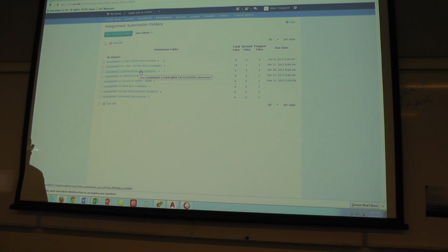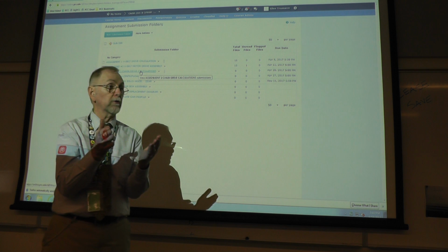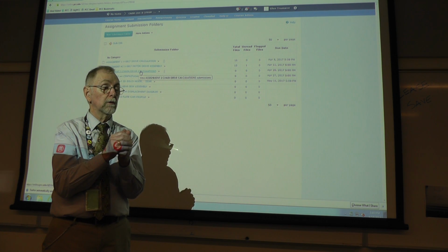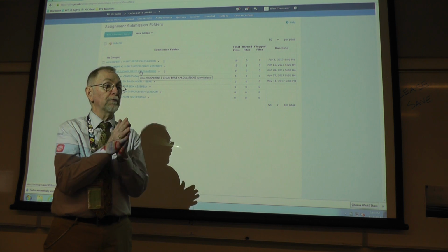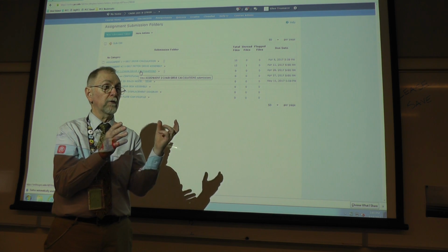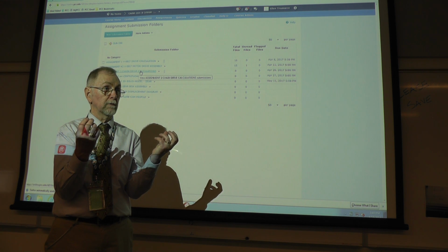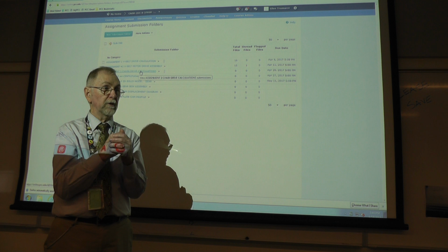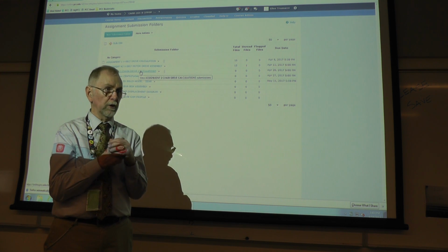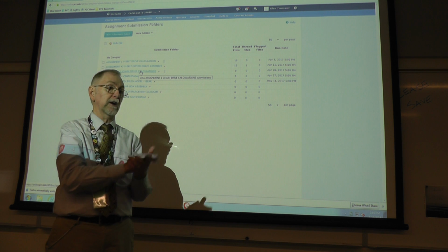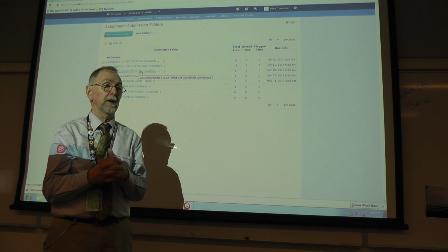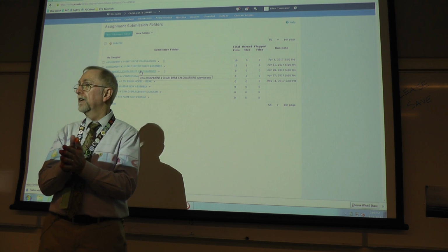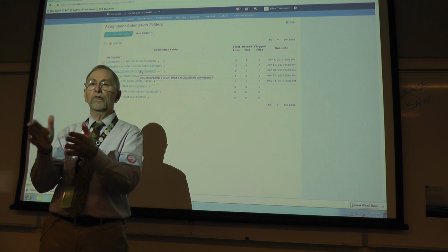Yeah. What does F look like? F is simply the number of teeth subtracted from each other. How do I recognize that in a paragraph? Well, first of all, you have to determine how many teeth both sprockets are going to have, and then you just subtract the number of teeth. It might be better if I work with you more individually when you're working on that actual design calculation, and then I can help you with that. That's what F is, and you need to get F to determine what S is from a chart.